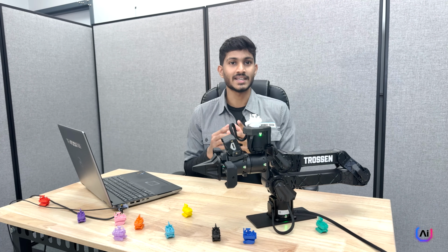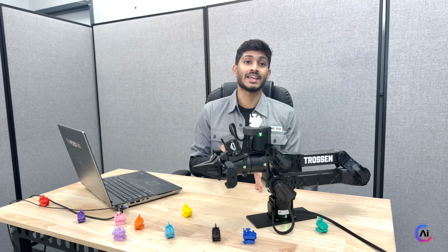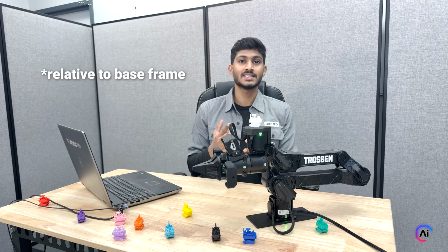Next up, let's talk about the Cartesian-based control. This update introduces a set of really cool features that allow you to control the robot directly in the tool space relative to the end effector's frame. Now, why is this important? Most of the high-level tasks, like reaching a point in space or applying force on a surface, are best expressed in Cartesian coordinate systems. Instead of controlling each joint individually, you can command the position, velocity, or effort of the end effector tool and let the system take care of the inverse kinematics.